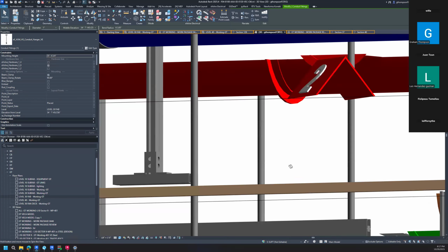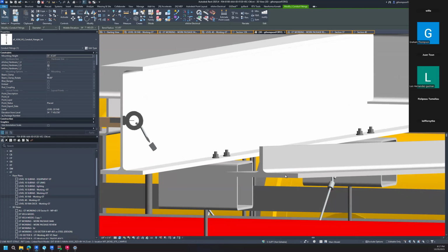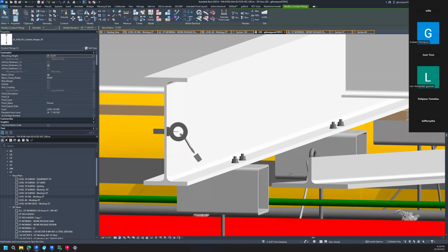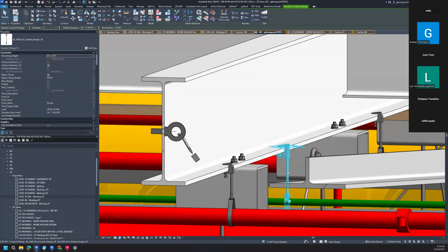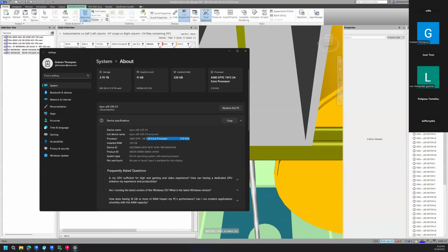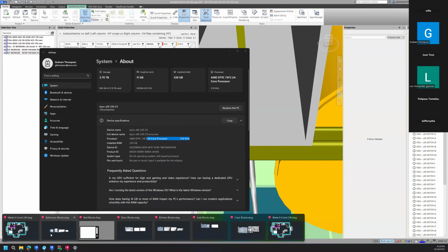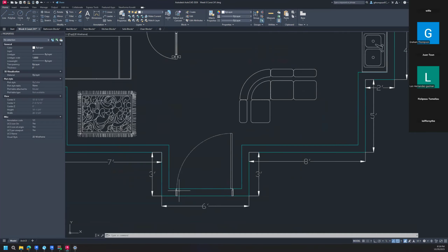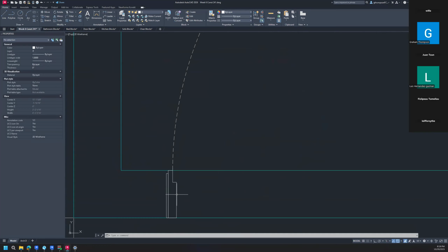Hey, I've got a question. Graham, go for it. I had a real quick question on the AutoCAD for the door jambs. Did you just explode it and then adjust the jambs to the length of the walls? I did. I exploded the whole thing, and then I just took that jamb and dragged the geometry of that jamb.